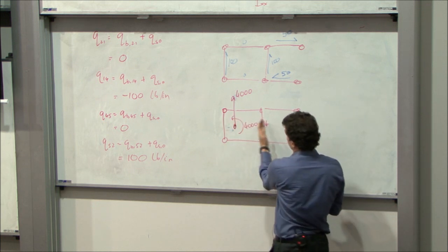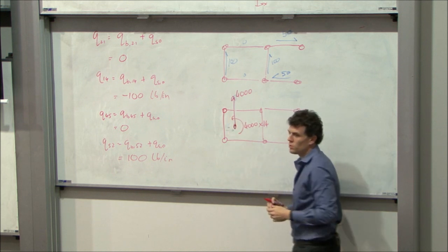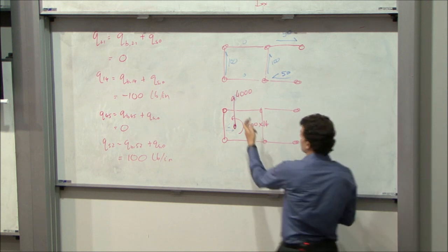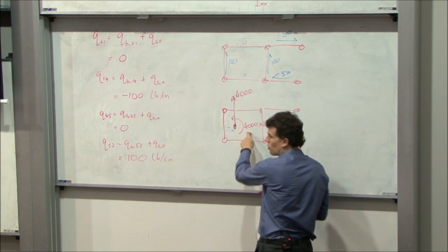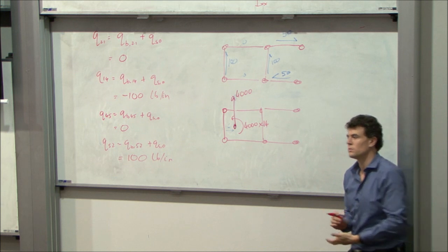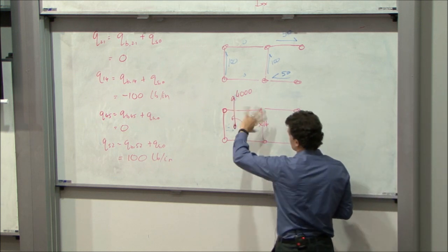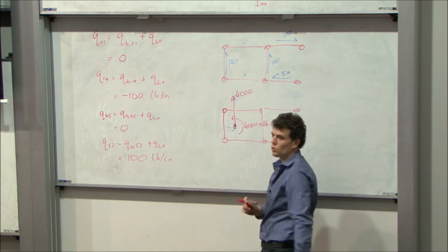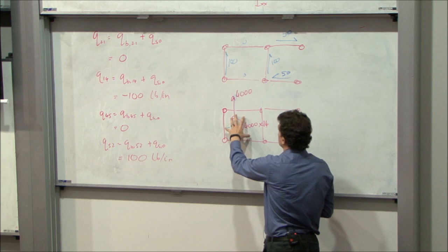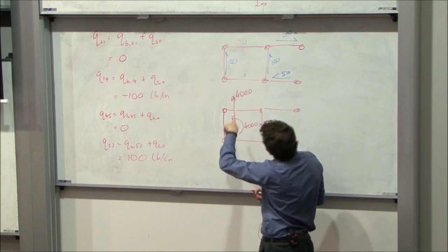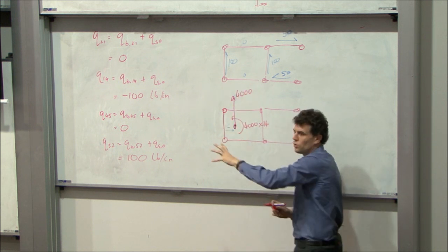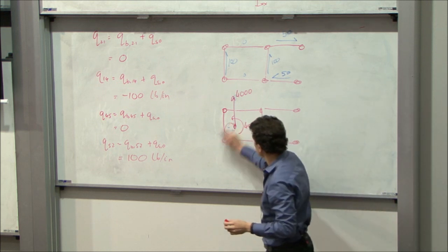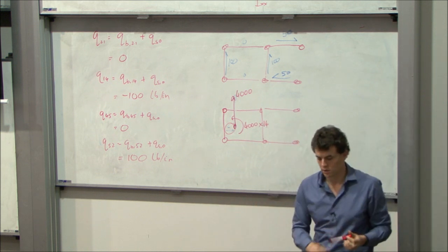So we've moved the force 14 inches, so we need to have a moment that gives us the same force system as we had before. And then you would solve the shear force and the torque bits separately, and add them to one another. The torque's very easy. We know that's just reacted in a loop around the closed section. The shear force, we have to go through the process we just did, and then we sum those two things together. But the calculation of where the shear force is not particularly easy.